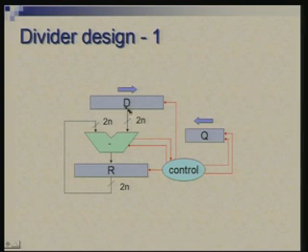This d shifts right by 1 position every time, q shifts left by 1 position every time, and on the right side we will insert a 0 or 1 as the space gets created in q. There is a controller sitting here which will look at the result of comparison. Basically, we are also assuming that this subtractor is doing comparison. The result of subtraction is available actually at the output of the subtractor.